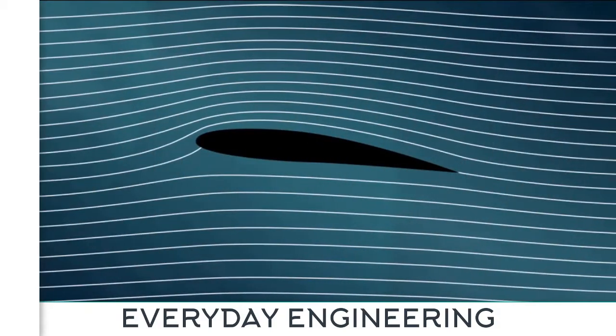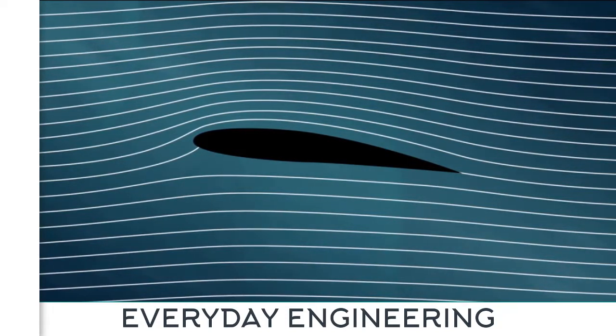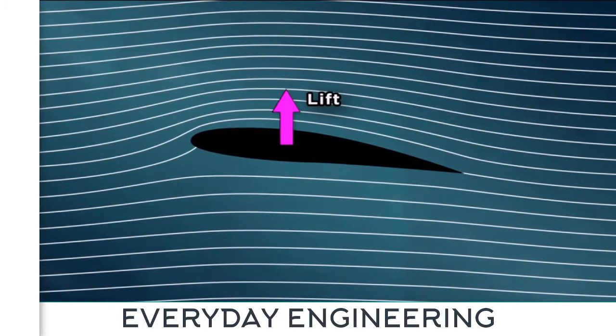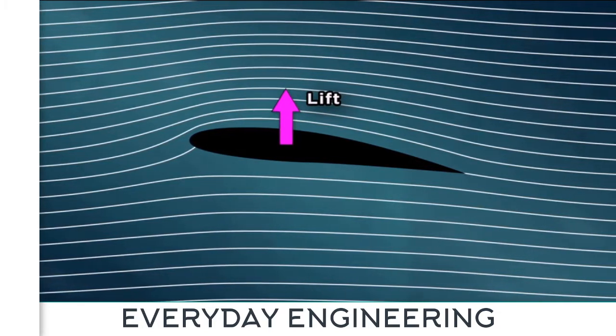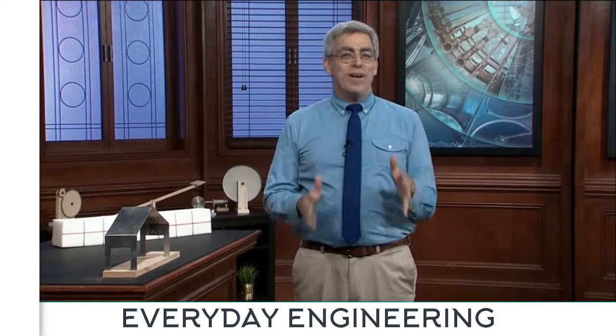By the way, the wind-induced uplift force on a building is entirely analogous to the lifting force generated by air flowing over an airplane wing. And in both cases, the Bernoulli effect is the underlying cause. Of course, there is an important difference. Uplift is highly desirable for an airplane, but it can be quite problematic for a building.